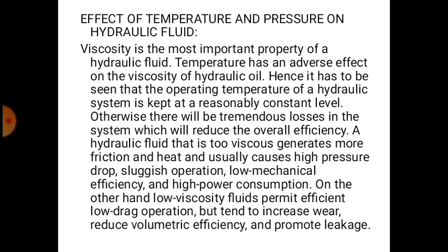Effect of temperature and pressure on hydraulic fluid. Viscosity is the most important property of hydraulic fluid. Temperature has an adverse effect on the viscosity of the hydraulic oil. Hence, it has to be seen that the operating temperature of a hydraulic system is kept at a reasonably constant level. Otherwise, there will be tremendous issues in the system which will reduce the overall efficiency.